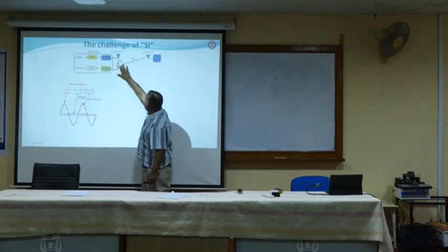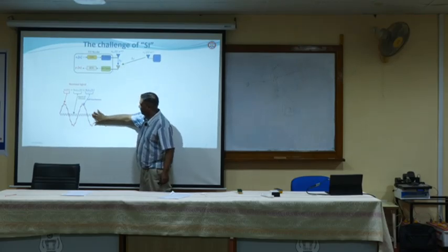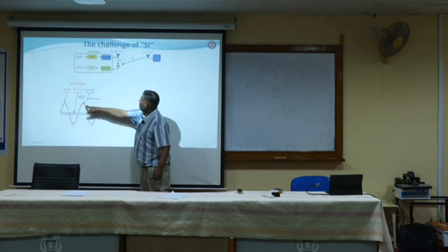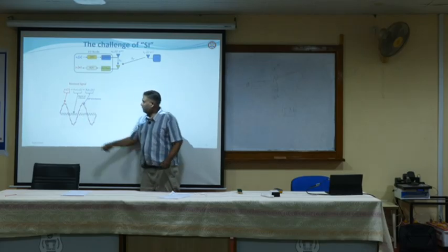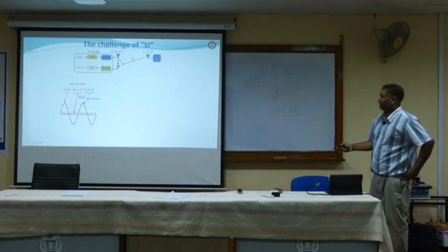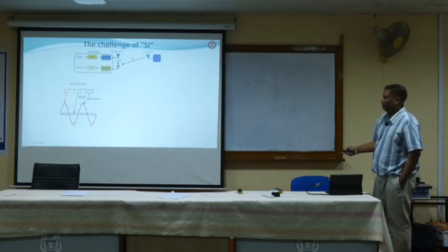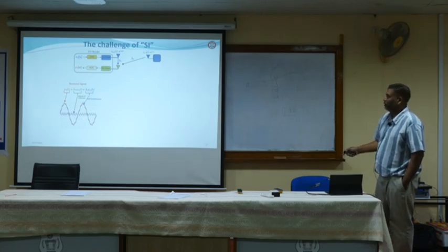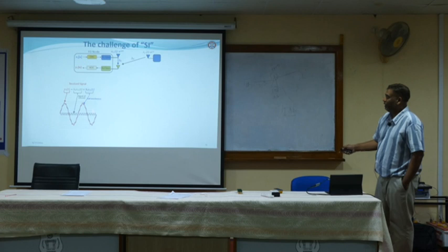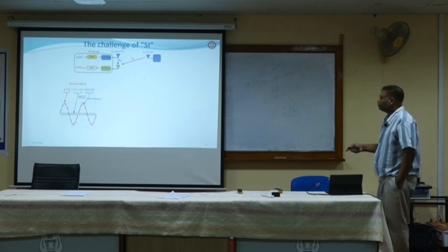The self-interference, the blue signal, is very strong, and black plus blue gives you the red signal. The received signal at this point is the red signal, which consists of the black signal and the blue signal as well. The blue signal is the self-interference that we need to cancel, and if we cancel properly, we can extract the black signal.